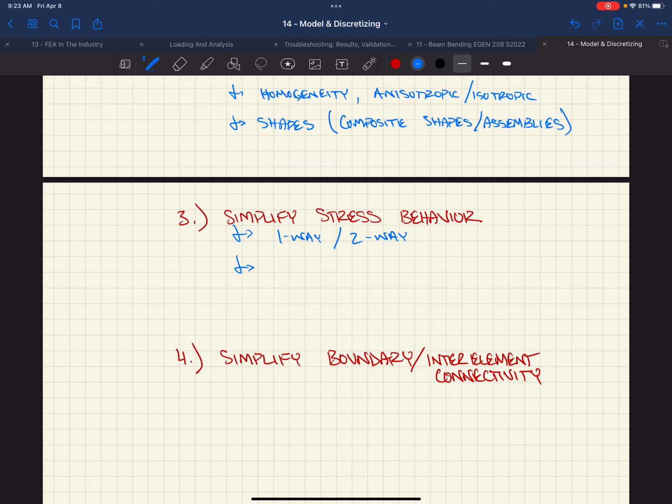I mean, the 2-to-1 ratio, right? Do you still assume the two-way action when you have a concrete on metal deck where the cross-section looks something like this? Right? And so you have a very specific strength direction. So even though the aspect ratio for this panel does this, you're going to land this deck so the flutes go like this, right? Do you still assume one way? Concrete says you might be able to assume two way, right? It's up to you. I'd assume one way. Your deck doesn't span two-way.